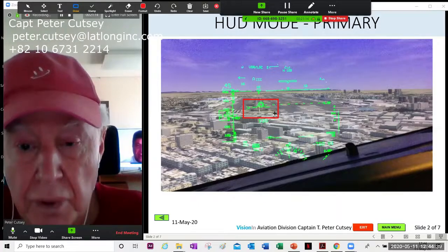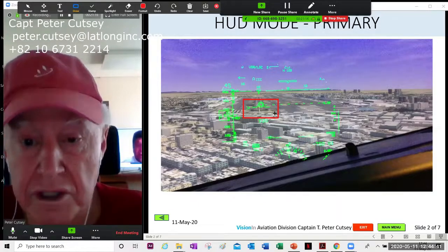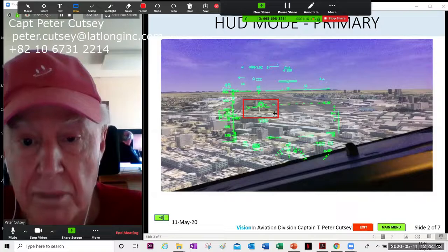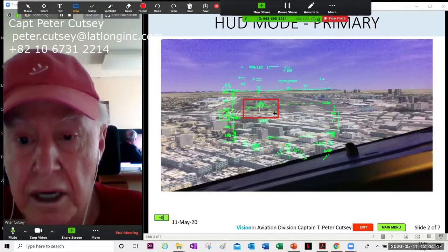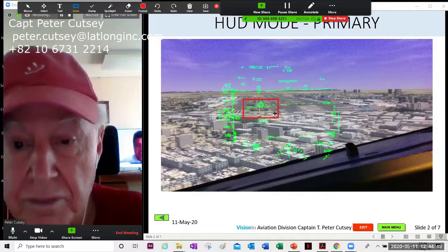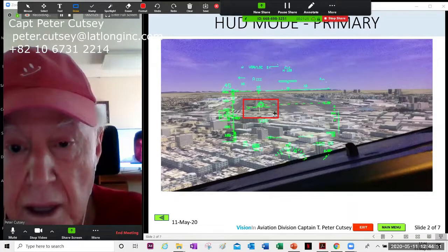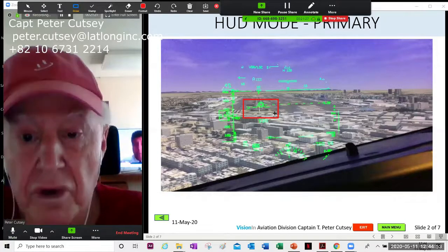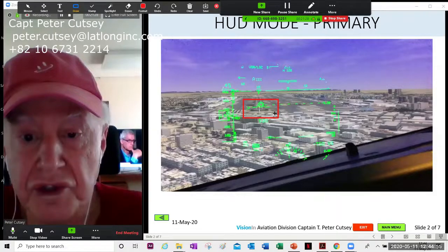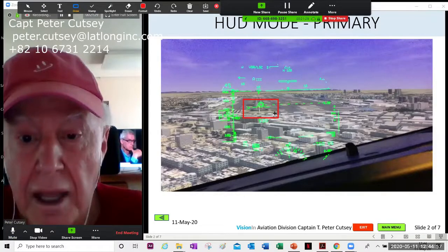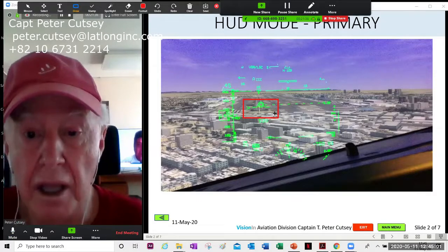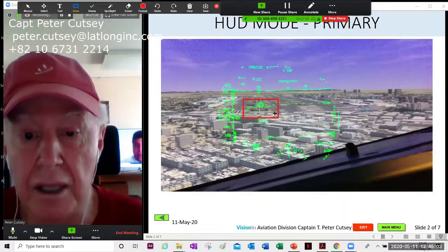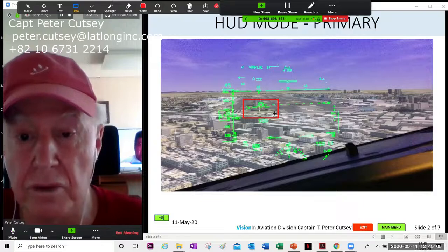So it's important in your training that your instructor stresses this, that the pilot monitoring is heads down, monitoring everything. He's in and out, in and out, in this case, because it's a VMC mode. But the pilot flying's focus is on the screen, and he is changing his focus to see the symbology on the combiner, looking through it to the poppy. You can see the poppy there, 2 red and 2 white.